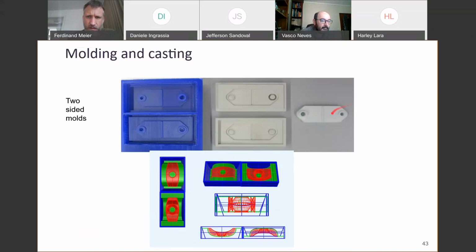So he invented this piece that he wanted to make a lot of copies of, and it's impossible to get silicone into these small holes. So I ended up drilling a small hole in the middle that goes through to the other side, so that your air can escape. If not, you're going to have a lot of trouble getting silicone into small cavities like this one.